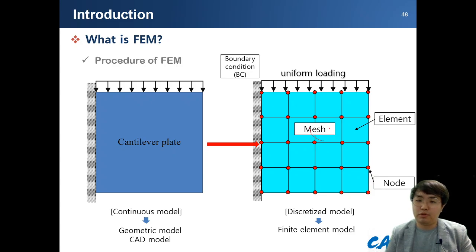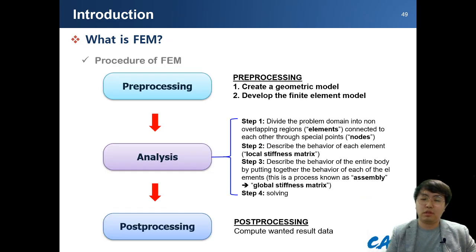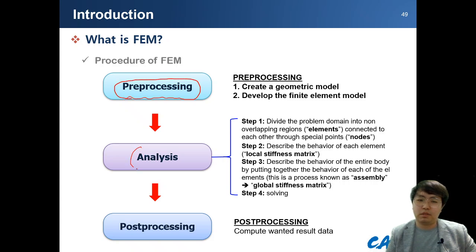After obtaining a well refined geometry mesh, you apply boundary conditions, for example uniform loading or fixed boundary conditions, and then apply your physics in the FEM technique.